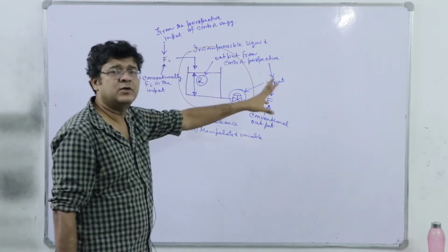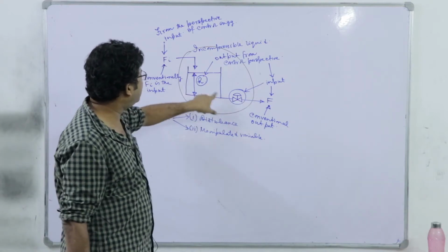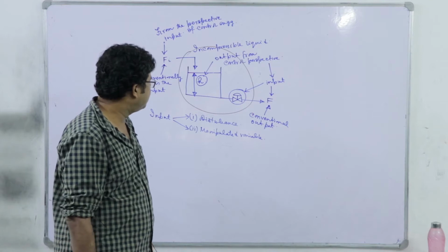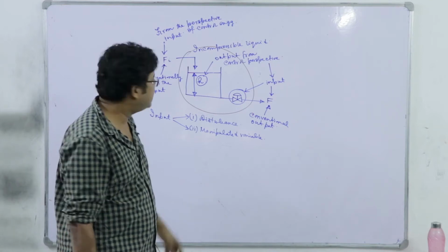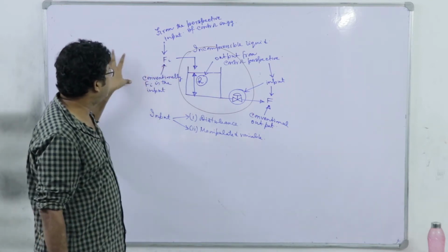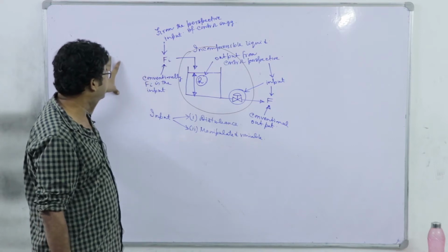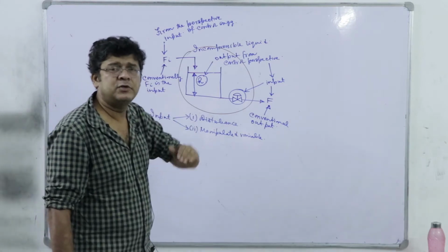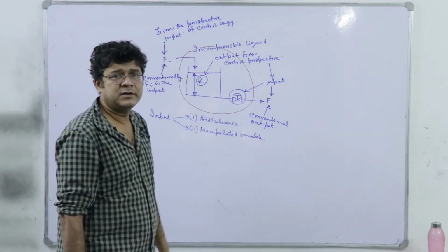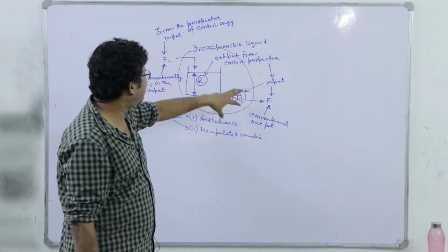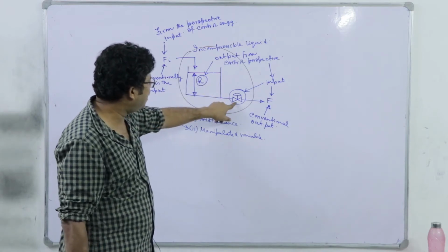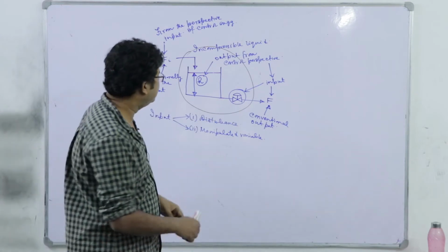F is also equal to 50 liter per minute, and for this given area, there will be certain value of H, which is the steady state level. Now Fi, because of some disturbance in the pump in the far upstream, shoots up to 60 liter per minute. So there will be a new level achieved by the tank if I am not operating that valve.